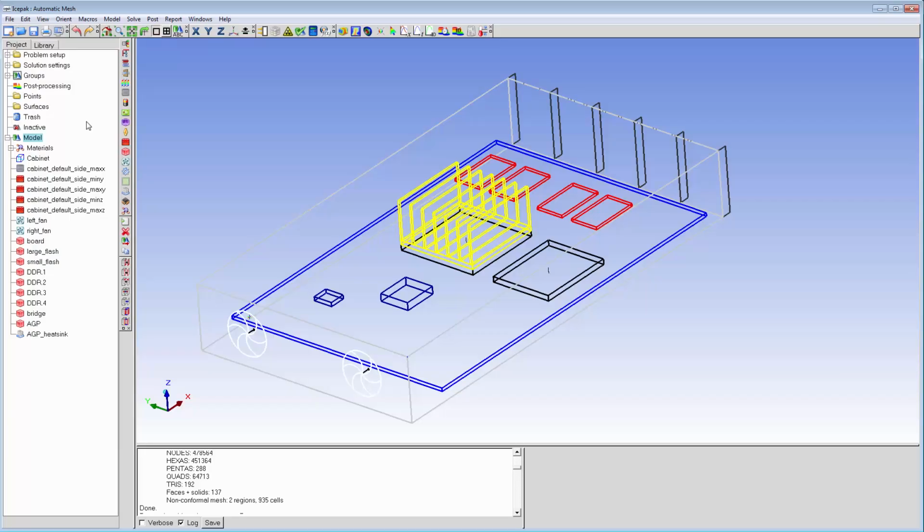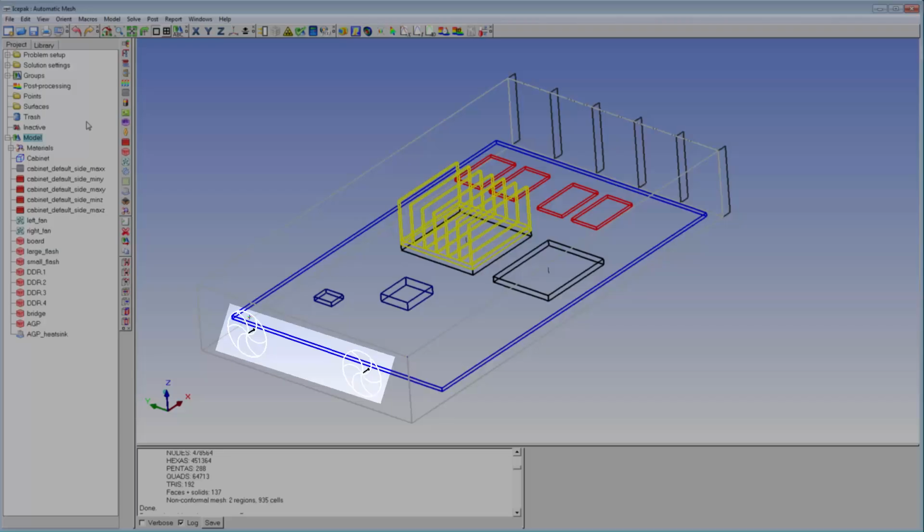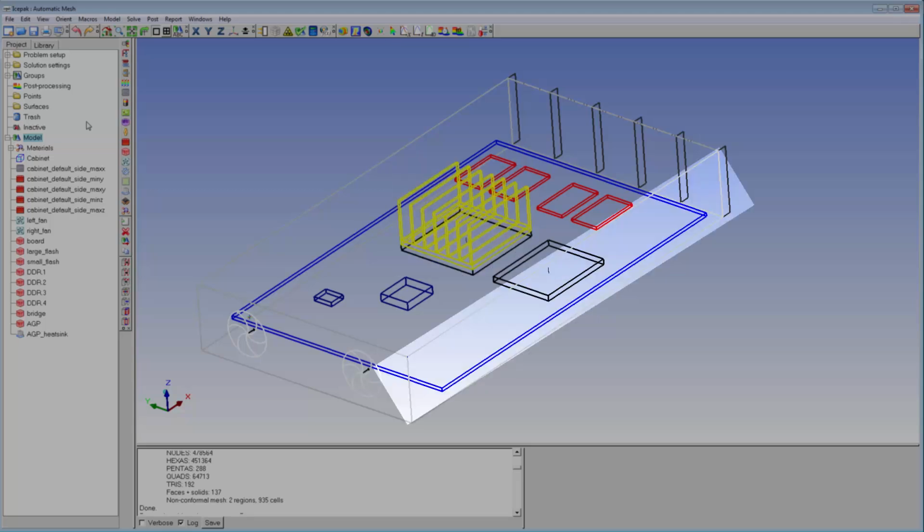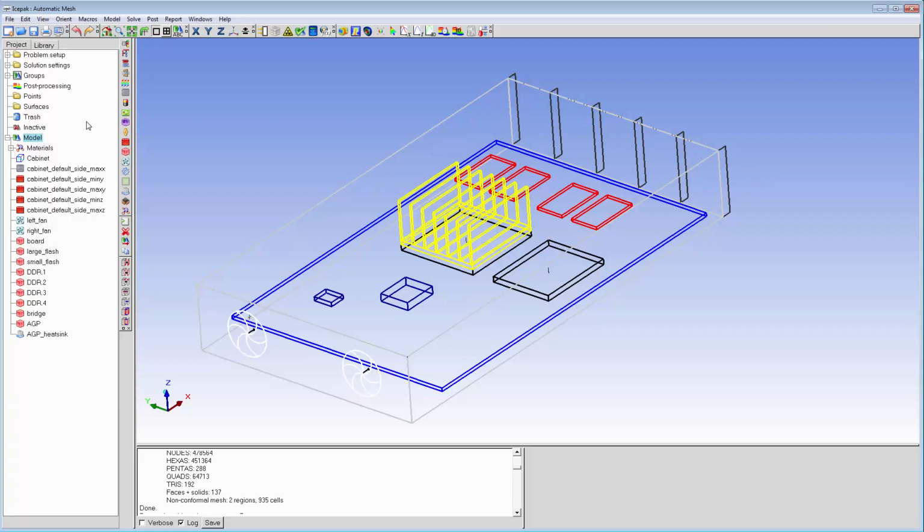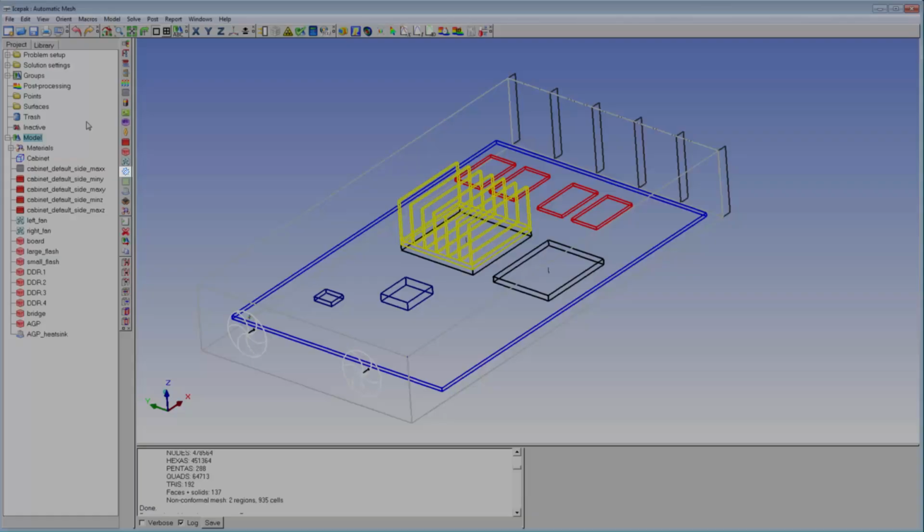The Automatic Mesh Settings macro modifies the global and per-object mesh settings for select object types. In the model shown, these object types include fans, blocks that dissipate power, a heatsink, walls, and a grill. Additional supported objects that are not included in this model are blowers, 2D sources, heat exchangers, and openings.